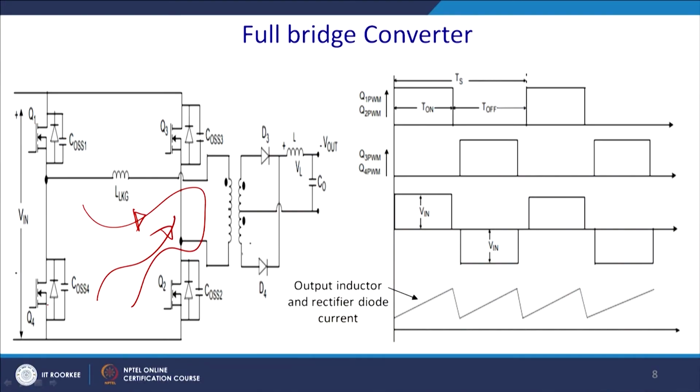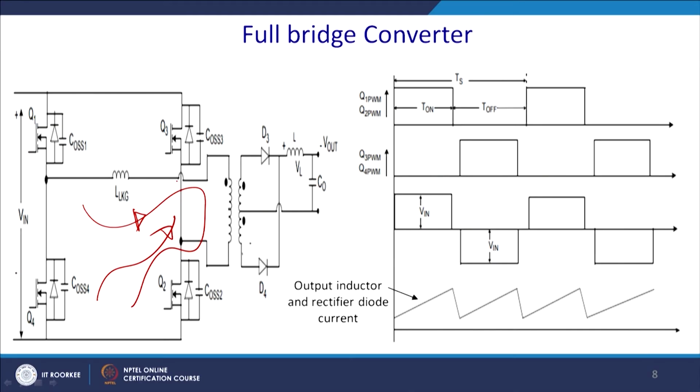Here you can reset the flux. Since Q1 and Q2 conduct, there will be a gap where the diode will conduct, and thereafter again Q1, and thereafter Q3 and Q4 conduct. So, automatically the flux will reset in all the places, and it has a huge rating. It can actually handle a rating the same as the supply voltage.